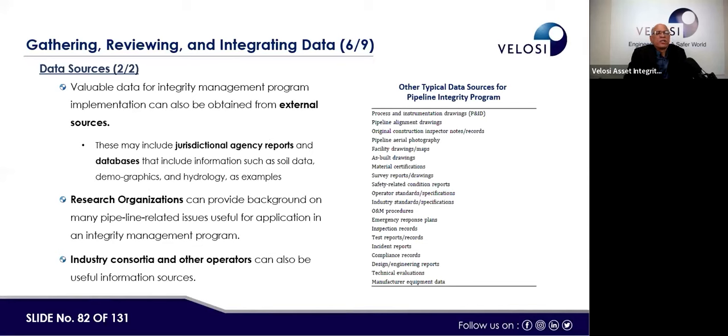Then, as information sources, one is the documentation. Then there are world organizations from where we can get some standard reliability data. For example, there is OREDA, from which we can get failure rates or standard reliability data, and some information can be gathered from API 571 and API 570.